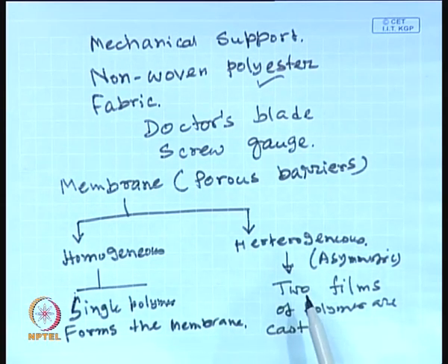If you get something very low, let us say 1 liter per meter square hour, that means if you provide 1 meter square area, you are getting 1 liter in 1 hour, that is very low, and it is not feasible for a practical operation. But if it is 200 liter per meter square hour, then it is quite feasible. So, that is called the productivity of the process, and this liter per meter square hour is known as the volumetric permeate flux or the volumetric filtrate rate.